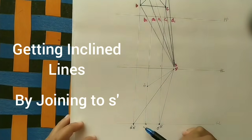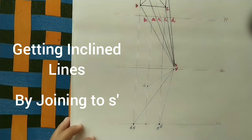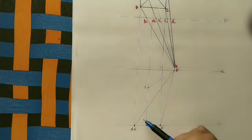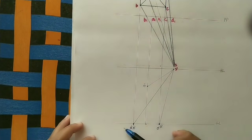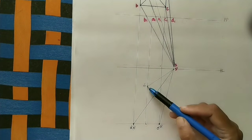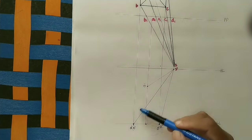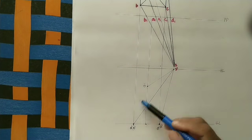Join all these A, B, C, D and apex points to H dash with the help of a scale, getting inclined lines. After getting these points, on the ground line we have marked the apex also. This height is 6 centimeters we took. After that, if we join all these points, we will get the side view of the pyramid.